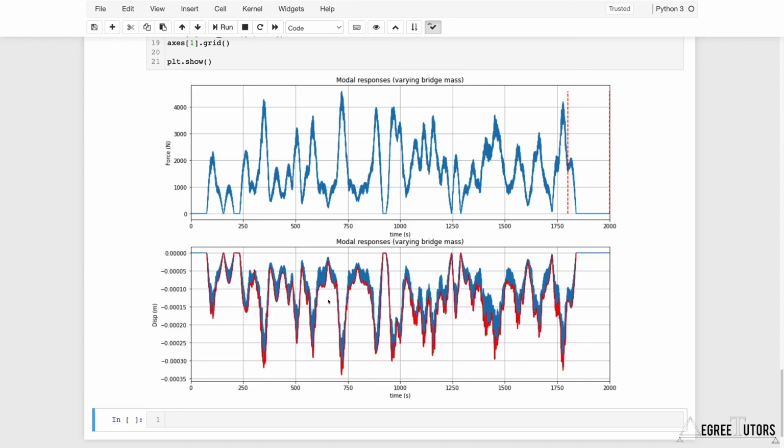Now, as I've emphasized plenty of times now, we're just dealing with a simple footbridge here, a simple linear structure, but you could just as easily map everything we've done onto a two-dimensional floor plate, provided that you have the mode shape for that floor plate, and that at any location you can identify the mode shape value and obviously the natural frequency, and all of this would map directly onto that. So that's worth looking at because you're probably more likely to be wanting to understand the response of a floor within a structure than a footbridge, a slightly more common use case.